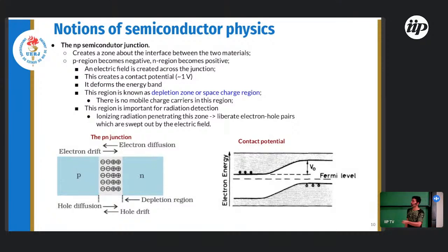Okay. When you do this, it's not a matter of simply putting them together. We have special techniques, with engineering, with very difficult things to do to put them together. Anyway, at the beginning, before equilibrium, we have an excess of electrons here and an excess of positive holes here. Due to diffusion, the electrons will go to the other side and recombine with the holes, while the holes in this region will move towards the N region.